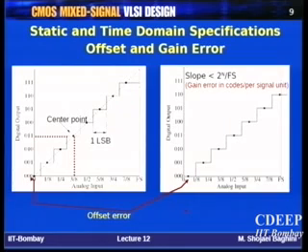Okay, now we come back to transfer characteristics. These were a few, like SNR, dynamic range, SNDR, and SFDR. So these are some of the important specifications when we are looking at the nonlinearity and nonidealities of the data converter. Eventually even quantization is some sort of nonlinearity we are applying to the signal. Now in the time domain or in the DC case, which is a static case, what are the specifications? So coming back to the transfer characteristics, consider just the static characteristics.